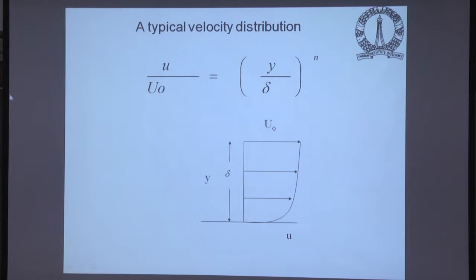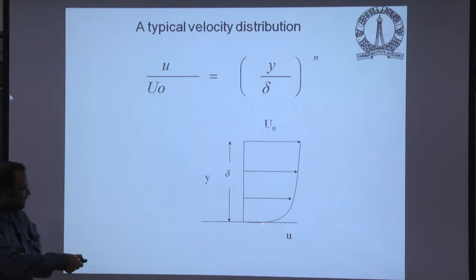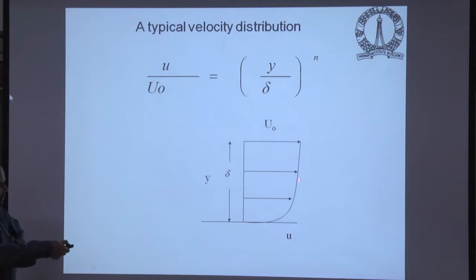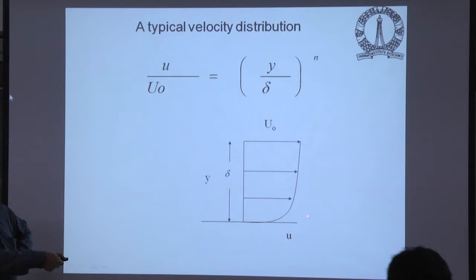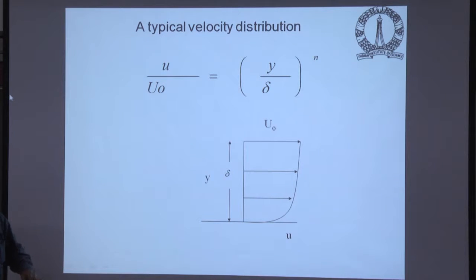That's how people started looking at a different description of the mean velocity. They said this power law description is going to be misleading, mainly because it fails to take into account the two-layer description. You see, there is a region where there is a slow change here in velocity. The mean vorticity, so to speak, is very less, whereas here it's very strong. So the idea is, somehow if I can zoom into this region by some trick, I can see that in great detail and address that point. That's really what we're going to do now.